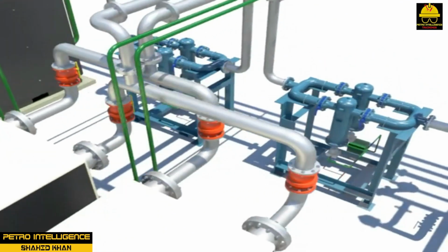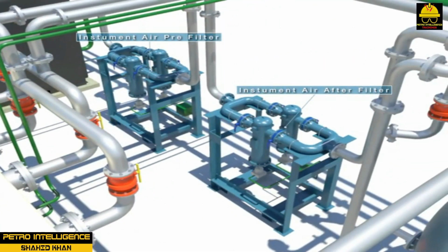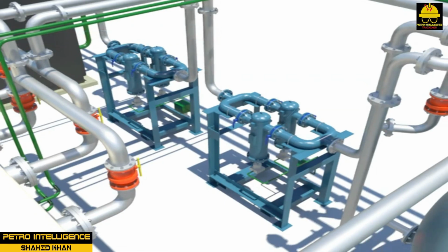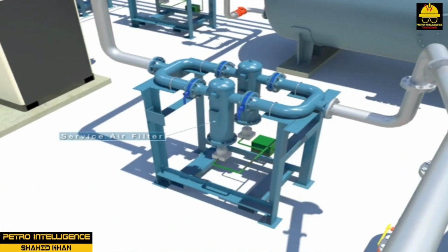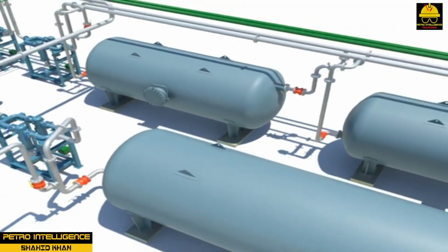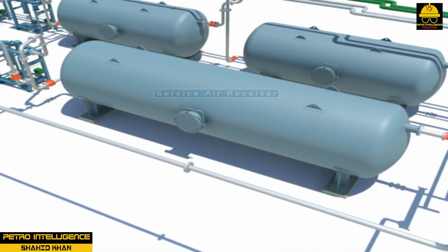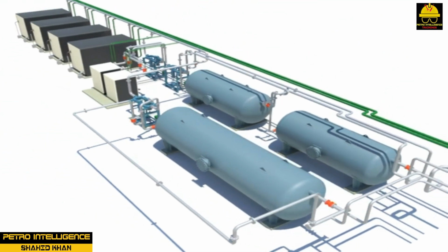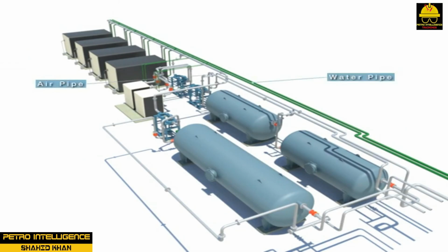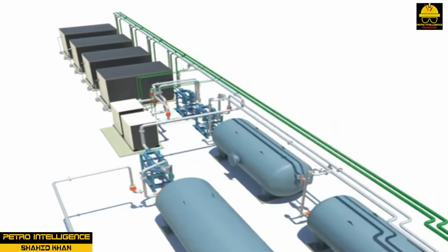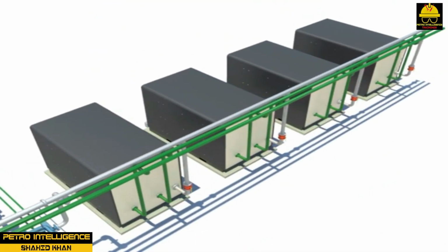It is important to maintain the instrument air system pressure at its normal controlled pressure of 105 psig, because some control valve actuators begin to malfunction when the pressure drops below 60 psig. At some locations, the plant instrument air system is protected against pressure failure by a tie-in to the nitrogen N2 system. Because of safety concerns, nitrogen is admitted into the instrument air system only during an emergency. An alarm or alert system is in place to warn all unit personnel whenever nitrogen is added to the instrument air header.